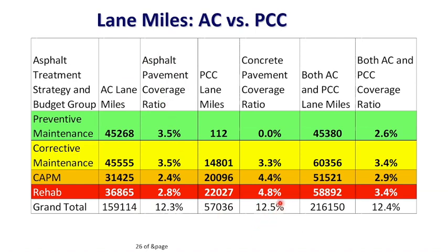PCC similarly, the network coverage ratio, almost every 8 years, 8-something years, you will still need to paint your entire PCC network again. This is crazy, right? This number is interesting. And then for PCC pavement, a lot of the length mile you have to paint by doing rehab, this type of CAPM type of job, or medium overlay equivalent type of job. So a lot of the network coverage percentage is centered around rehab type of treatment instead of preventive.